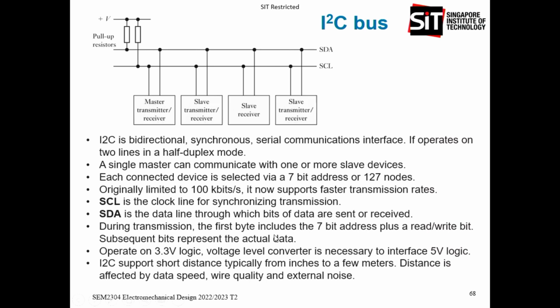This thing operates on 3.3 volts. And if you want to have 5 volts, you need to have a level converter for these 2 signals. So just be careful: whichever device you connect to must accept 3.3 volt logic. If you put in 5 volts, then you must have a logic level converter. Again, the distance for I2C is only limited to a few meters.